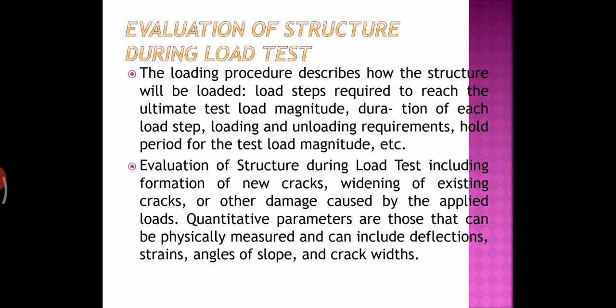Then, during the load test, we can evaluate the structures, or we can determine the formation of new cracks, widening of existing cracks, or other damage caused by the applied loads. Then quantitative parameters are those that can be physically measured and can include deflections, strains, angles of slope, and crack widths.